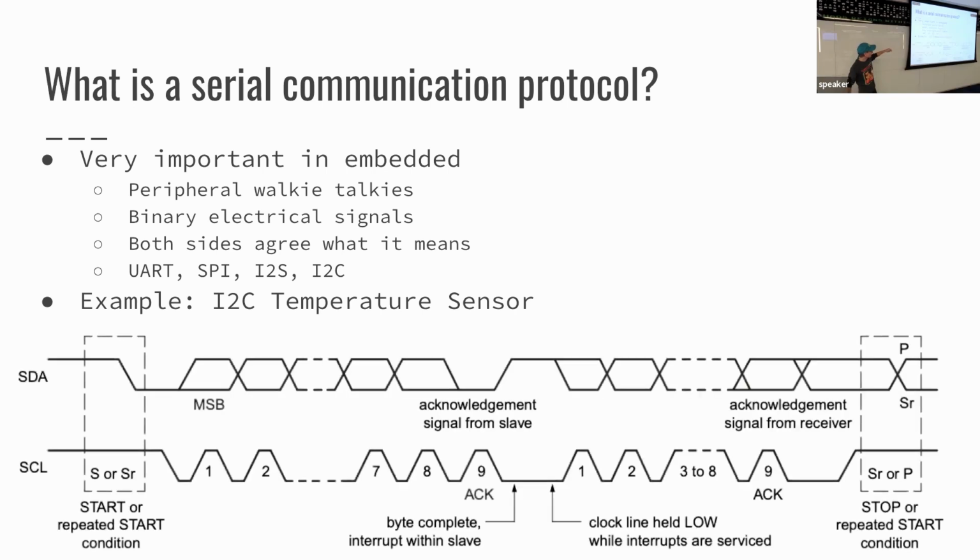The first one that I dealt with in a class was a temperature sensor, and if you're looking for little projects to try, it was a really good introduction to writing a driver for this sort of thing. This is the I2C protocol. This is what the temperature would be coming in. There'd be a temperature sensor on this side, 2 wires coming out of it, and then a microcontroller on the other side that is receiving 2 wires, and each side has an I2C interface, sending the temperature data on the serial data line, and the clock.